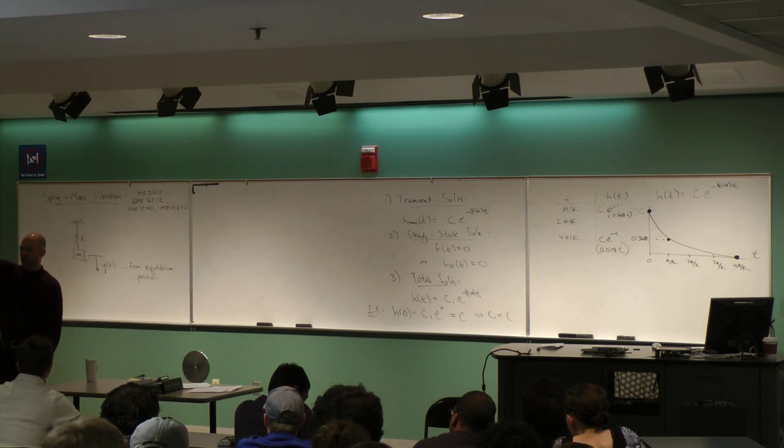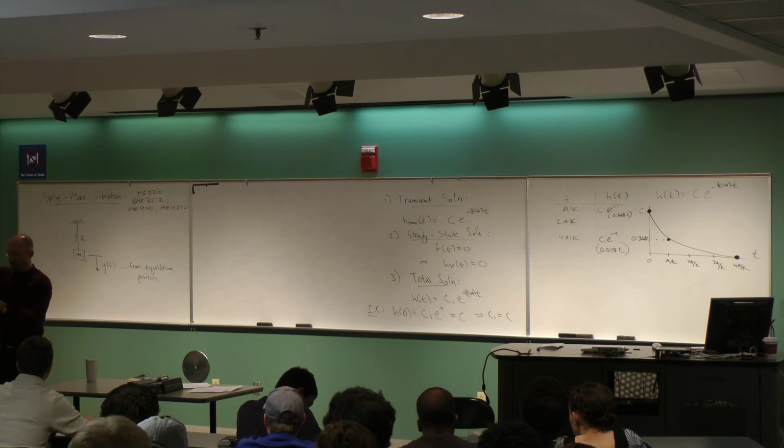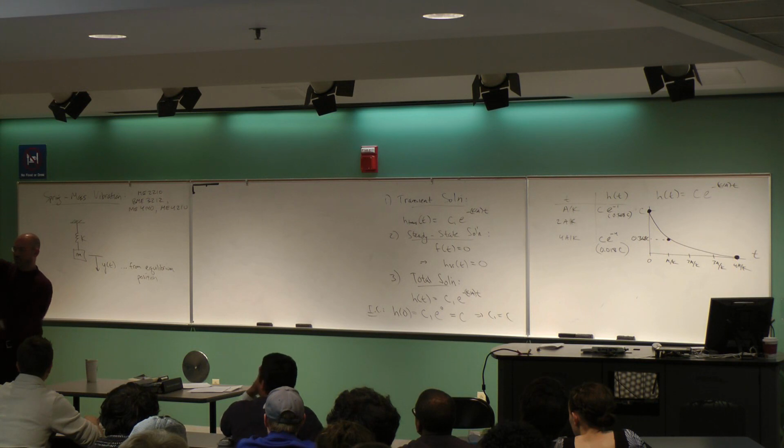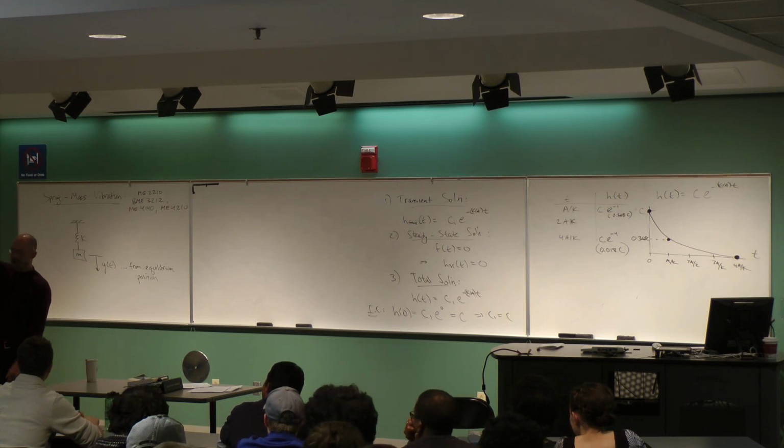It's got a certain length to it, undeformed. If I put a mass on a spring, independent of it being a dynamics problem, and I just statically let it stretch the spring out, clearly this spring, a statics problem, it's not oscillating now, but the spring's a heck of a lot longer than it used to be. And so now, if I call this 0 and displace it and let it go, it will oscillate about the equilibrium position. That is a different mathematical description than if I do this.